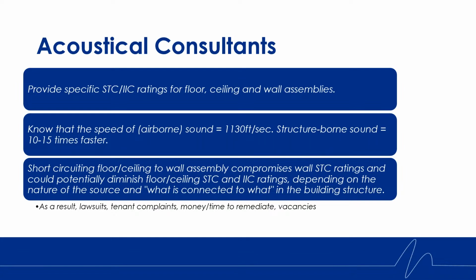Whether we're talking about low frequency or high frequency, it depends a little bit on that. But certainly, if we're structurally connecting materials and systems that should not be connected, it will absolutely diminish the STC and IIC.